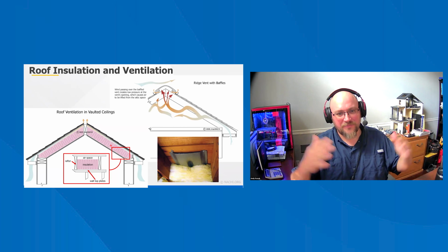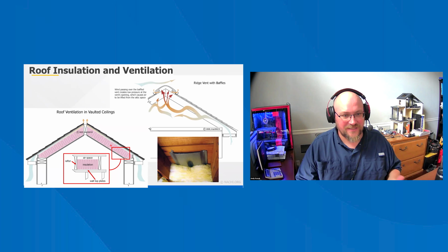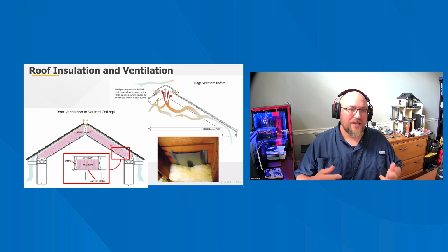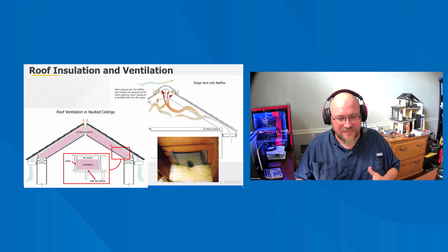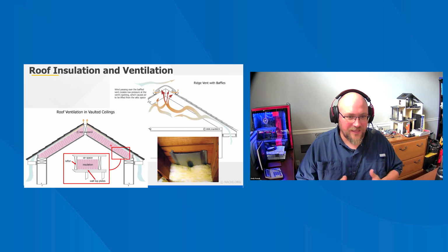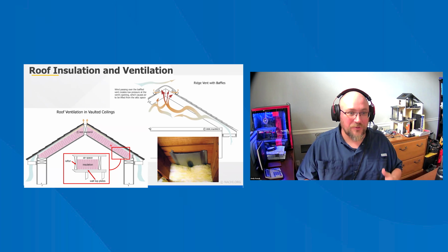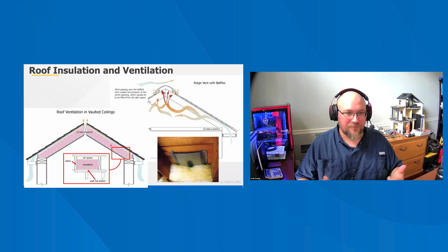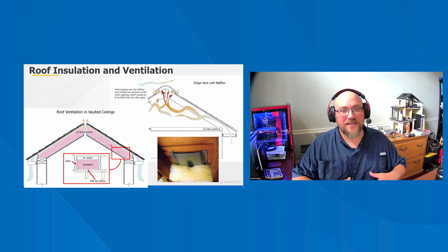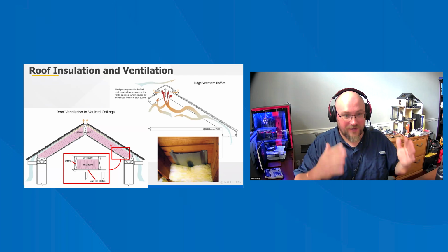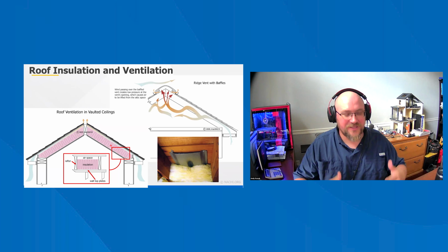So basically everything below that spray foam is now supposed to be considered conditioned air, right? Through all the building science, through the trial and error that we've gone through with this new building practice, new installation practice, now we know that we need to circulate that air, because if that air becomes moisture laden, it cannot pass through the spray foam insulation. There was no roof ventilation there because they spray foamed the roof decking.